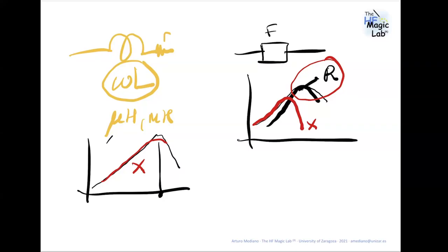The donut is a current probe. Yes, you can do something, but it's not easy, because when you are measuring differential mode and common mode in a cable, the measurements are very, very affected by the position of the current probe in the cable. So be careful about that. But you can do things with a current probe.